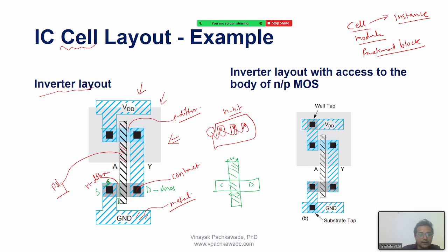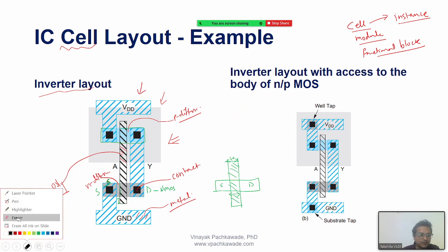Here I draw the diffusion region in blue. This is the blue in the center for the P diffusion. So that's my PMOS transistor. So again I am drawing it somewhere. So I extend this one, and somewhere here I am saying that I want my PMOS transistor.